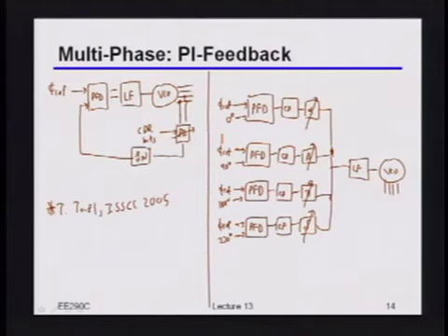Yeah? So can't you program the dividers rather than putting an extra coefficient? Program them how? I mean, it's a digital counter, right? So shouldn't that be easier to program? Well, when N1, you say N2. What do you mean, program? I'm not sure whether it'll work, but having different counts. Well, okay, so I believe what you're saying is similar to what Chintan was suggesting earlier, which was, imagine you just had a divider where you changed the feedback clock into that divider. So let's say on one phase you fed it with the 0 degree, and then next time you fed it with 90 degree, and you dithered between them. Is that what you're suggesting?